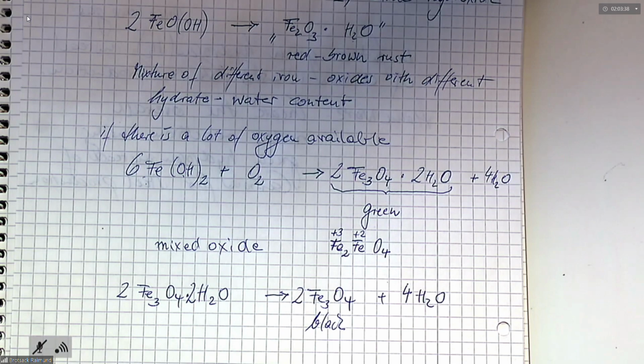We call it a sacrificial metal. You offer another, not so expensive and easily available metal, putting it into contact with the one which should be protected, and the one with the redox potential more on the negative side will be oxidized first, or spend electrons to protect the other one. Controlling the temperature conditions. Yeah, directly, what should the temperature help with?